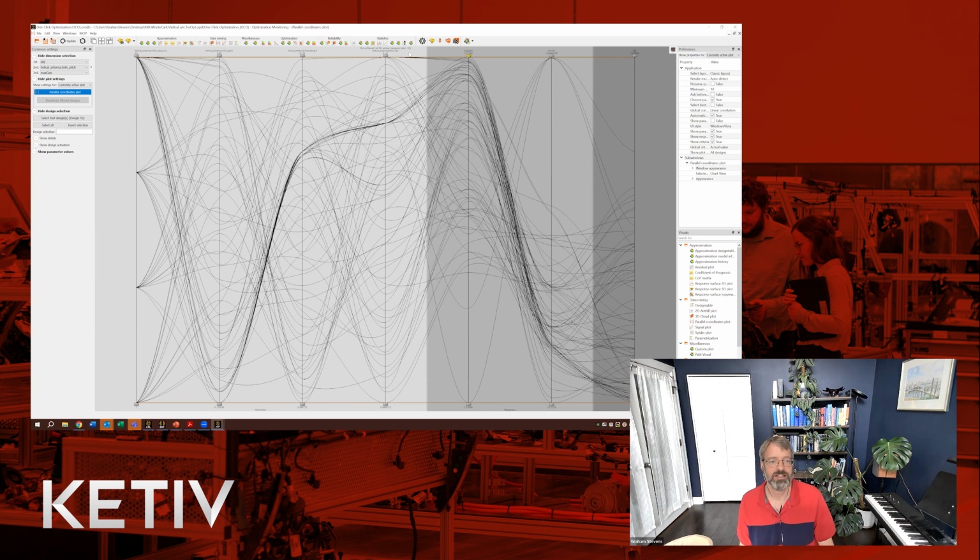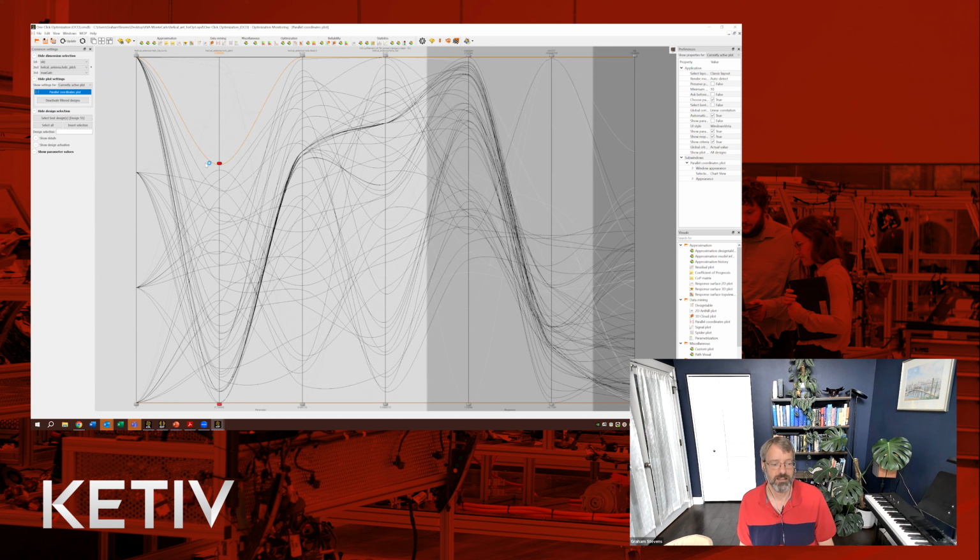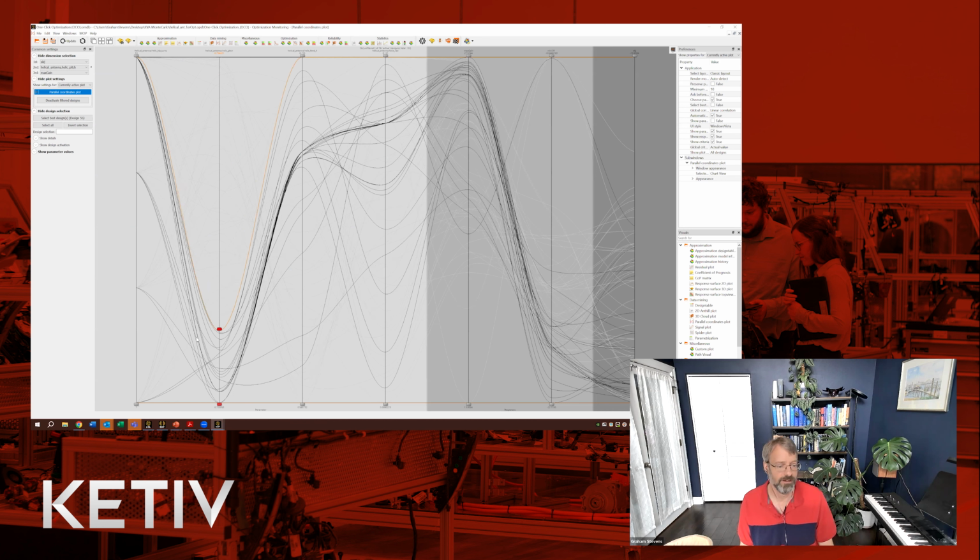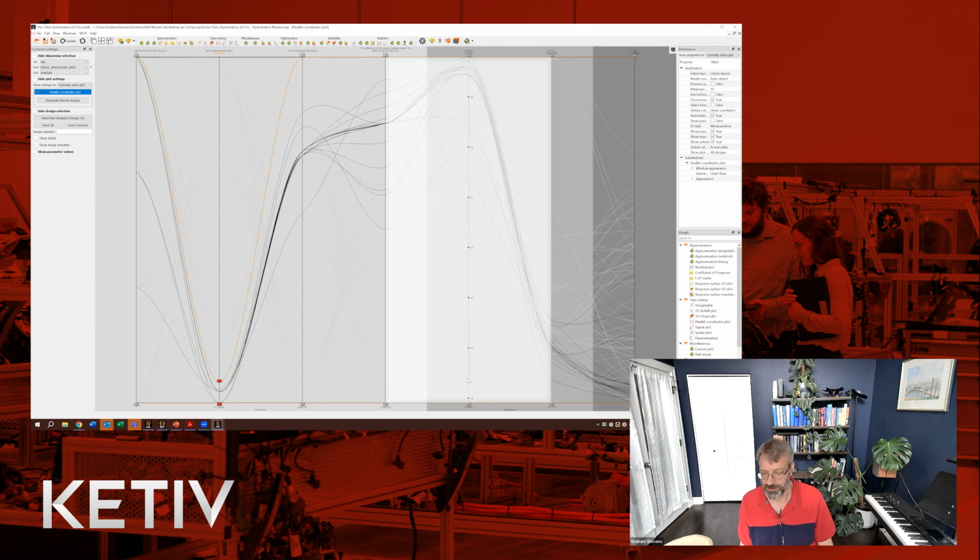I'm looking for max gain, and I can just vary some of the input, say helix pitch, and say, okay, I'm going to vary it from this to that, and now I can look at all of the different iterations that satisfied that to get to this maximum gain. Or I can say, I'm going to go my maximum gain to here, and I want to cut off all the rest of them.